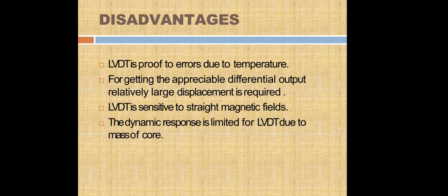Disadvantages: the LVDT is prone to error due to temperature. For getting an applicable differential output, large displacement is required. The LVDT is sensitive to stray magnetic fields. The dynamic response is limited for the LVDT due to the mass of the core.